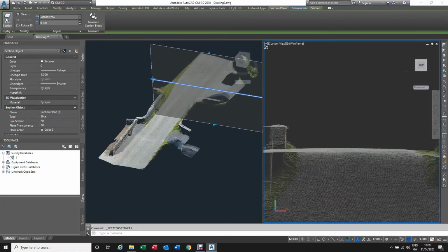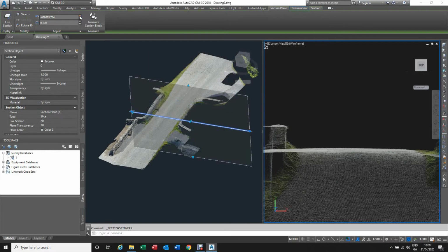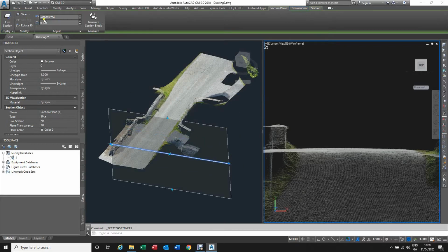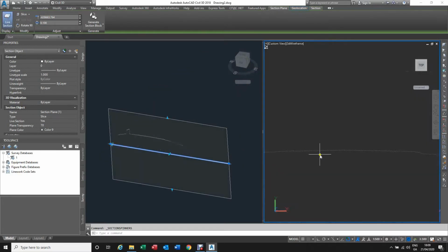If you want, switch on and off, and then you can see how I'm moving this forward, and I switch this off, and then you can start drawing. If you turn on the 3D snap with F4, you can snap to the point cloud and draw a line. This is more useful if you want to do a floor plan or a building elevation or something, so you can use that for that probably more than for a topo. I don't think it's good for a topo anyway.